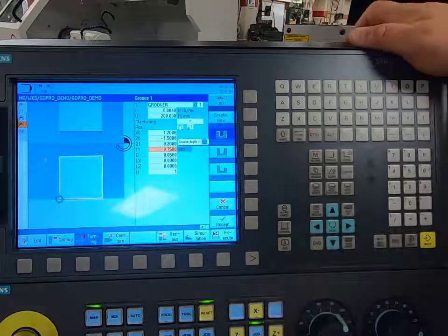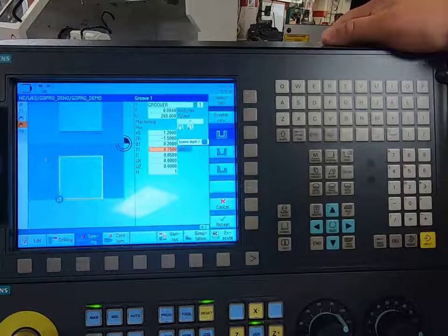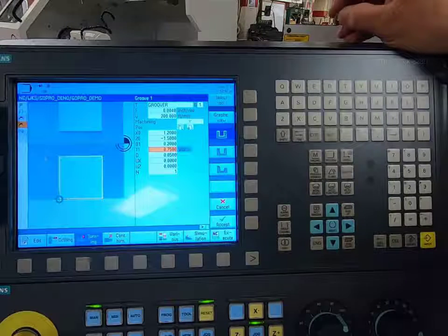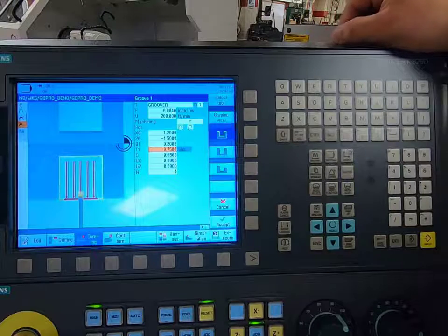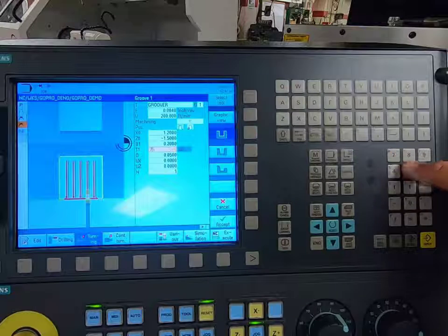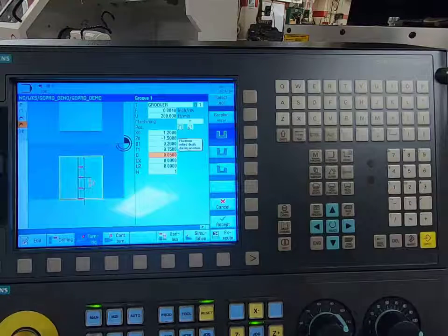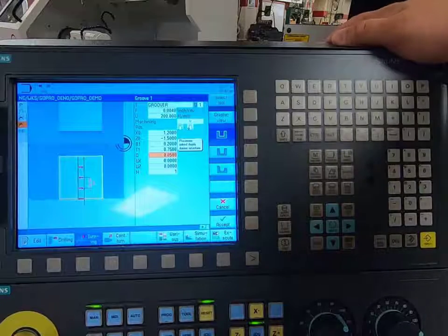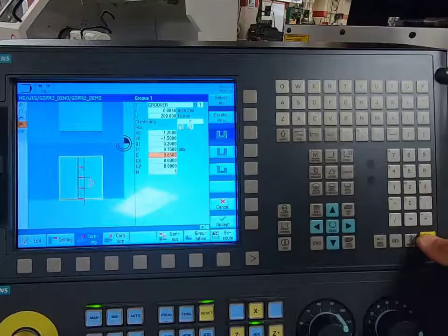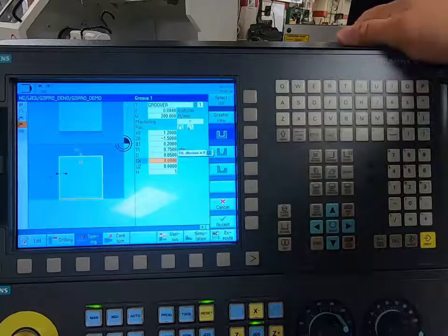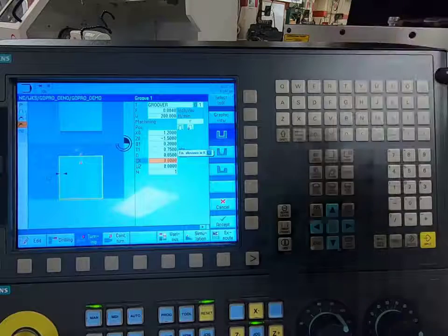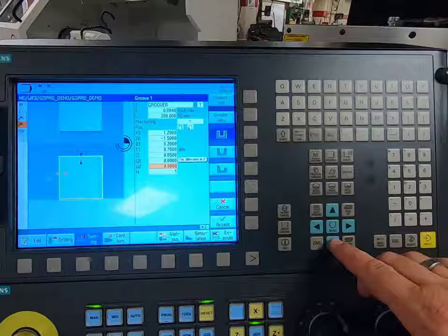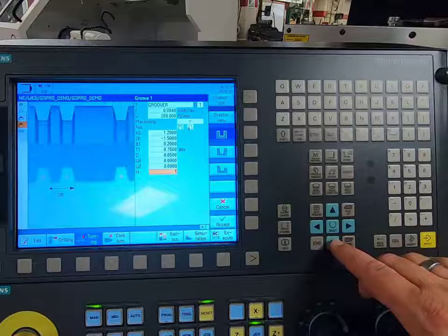Now this is the groove depth. Don't get lost on here. It is what the finished diameter is going to measure when you're done. In this case, my print is telling me it is 750 thousandths. And then I have a maximum in feed. I'll leave that at 50 thousandths. Right below it, I have how much I want to leave for finishing passes. Well, I'm just grooving, so I'm not worried about it because I have the tolerance. And I have my finish allowance in Z, so I'm good to go.